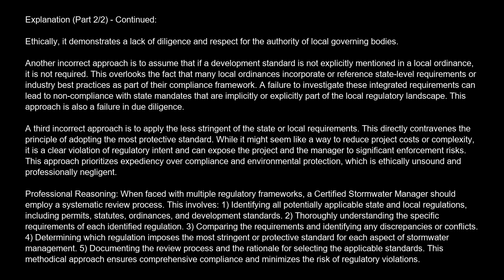Comparing the requirements and identifying any discrepancies or conflicts. 4. Determining which regulation imposes the most stringent or protective standard for each aspect of stormwater management. 5. Documenting the review process and the rationale for selecting the applicable standards. This methodical approach ensures comprehensive compliance and minimizes the risk of regulatory violations.